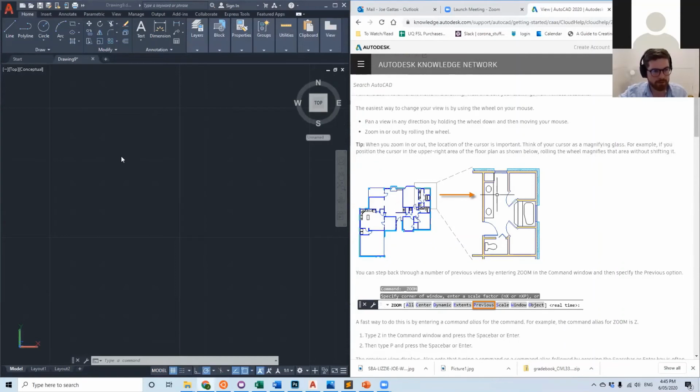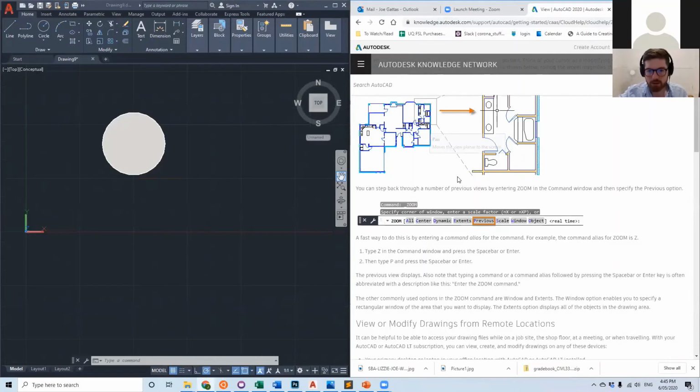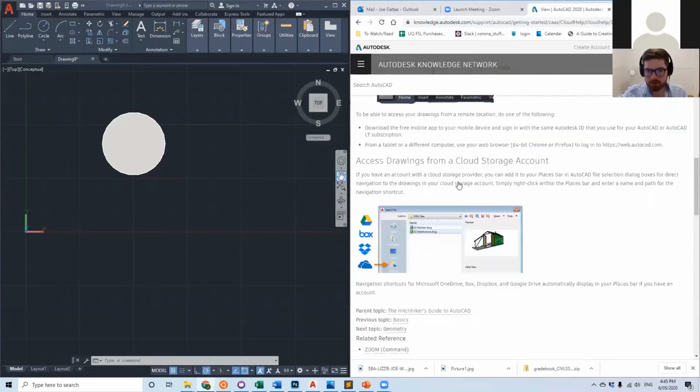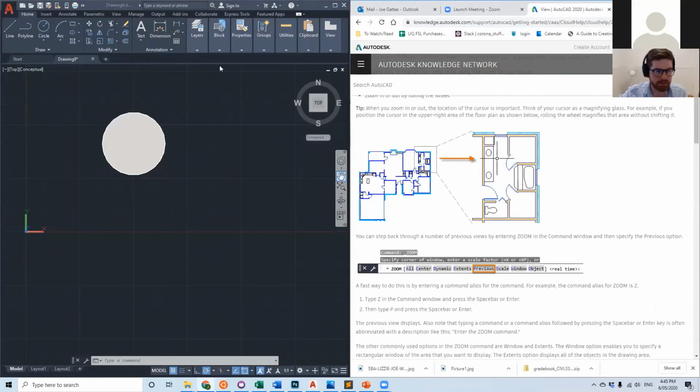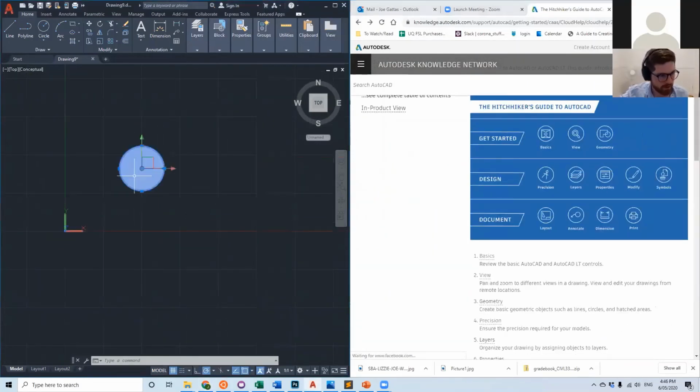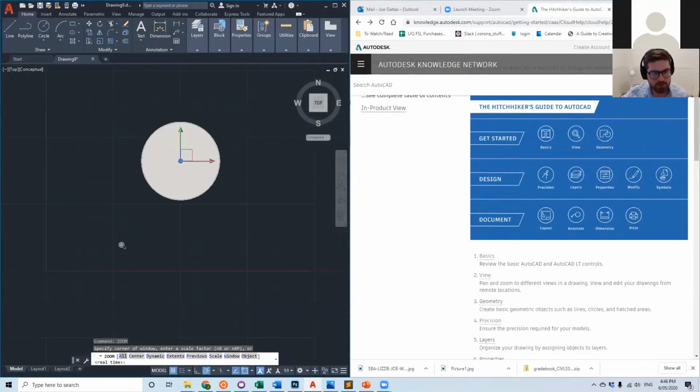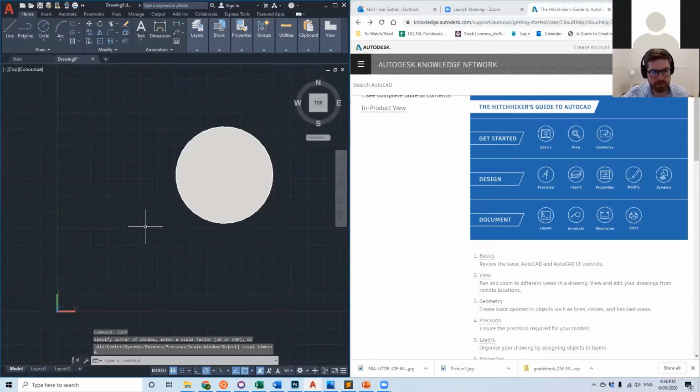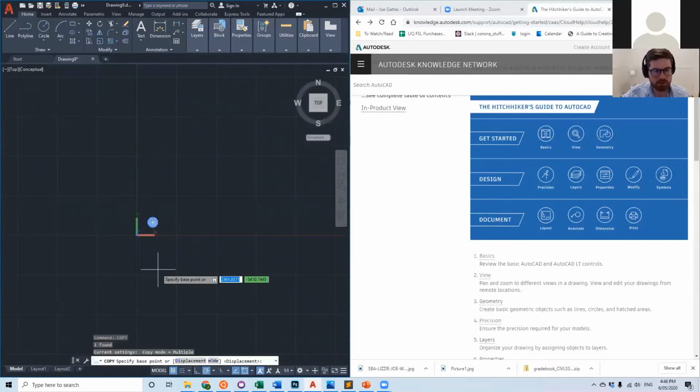I just mentioned briefly the mouse tools. I basically covered everything that you need there. A few other ones that I find super useful are zoom. I'm typing in zoom to the command window here. And when zoom comes up, you can zoom around all, object, or extent. If you zoom all, it will zoom in only on everything in your model. I'll show you a couple of objects here to show you the difference.